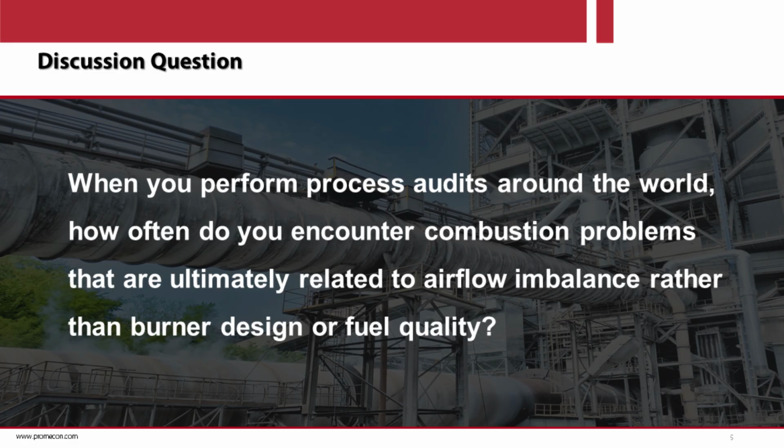That is why some of the operators primarily focus on the control of the primary air because they control the flame with it, and they rarely take care of the split between tertiary air and secondary air.